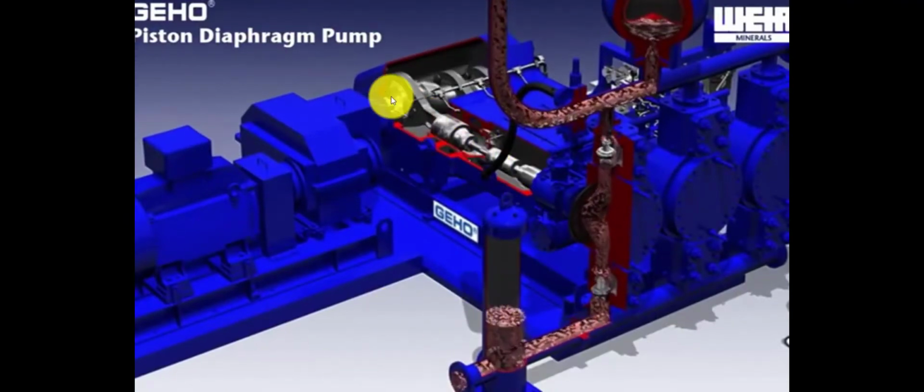So we have here the operation of a positive displacement or reciprocating pump. You have the electric motor with its corresponding RPM, then the reduction gear, because usually the RPM is very low. The advantage of positive displacement, piston reciprocating or diaphragm pumps is that they have a high pressure discharge. But the type of flow is pulsating. When we say pulsating, it is because of the fluctuation in the pump's operation, so it is a pulsating motion.